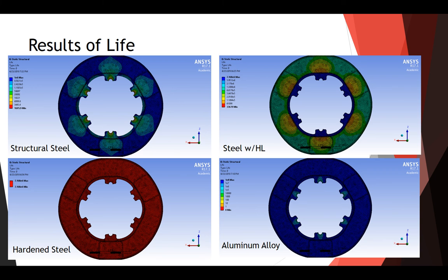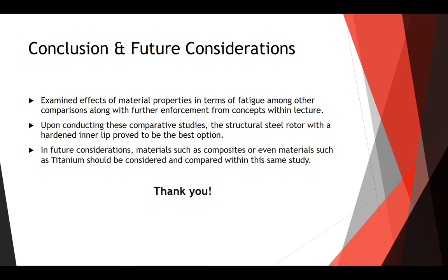If you were to manufacture this for a business, it supports all the criteria that you would need within racing applications. It's a safe rotor. It distributes thermal stress and temperature evenly, and it's well within the lifespan that you would need for a rotor within this application. So I thought that it was a good consideration in this.